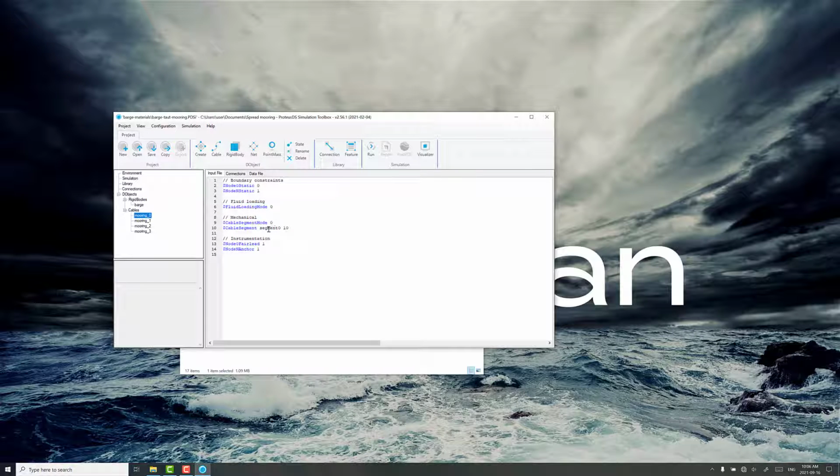Currently the top mooring assistant uses the older style cable properties specification, cable segment mode 0. So one thing we're going to do is go through and change this to 1. This is the new way of doing things with a state generator and data file. It's a little bit more robust, so you can resolve follower properties. It's going to comment out the cable segment property here. We'll need to do that for every mooring line for the moment, though expect the top mooring assistant in the future to replace these with cable segment mode 1, so you won't have to go through this.